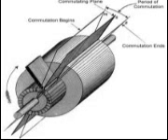The output voltage of a series wound generator may be controlled by a rheostat in parallel with the field windings, as shown in the above figure 9-15. Since the series wound generator has such poor regulation, it is never employed as an airplane generator. Figure 9-15: load diagram and schematic of a series wound generator.